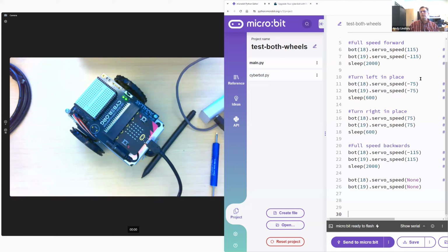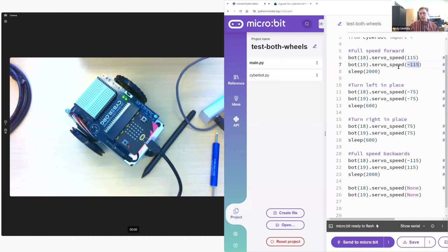What this one is going to do is go forward full speed, and it might curve a little bit. For each speed, you're going to have to probably test. It's not like a constant offset. It probably increases linearly with speed, though I doubt it's even linear. So if students have a set of favorite speeds they're going to use, pick your offset to slow down a wheel at a given speed. Don't do that though. We'll just let it curve a little bit and that's fine.